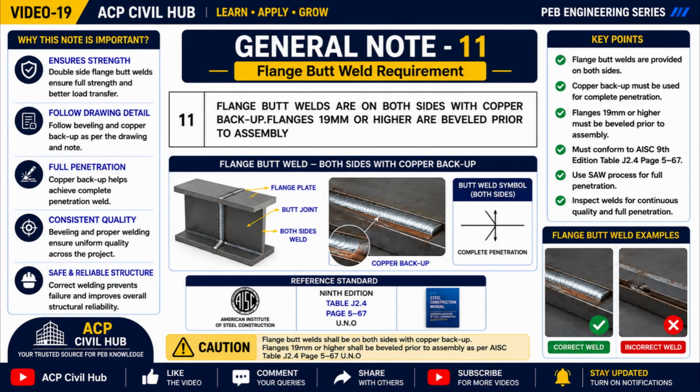The flange carries the highest bending stresses in a steel member. Therefore, the butt joint must develop the full strength of the plate without creating a weak point. To achieve this, the edges of thicker flange plates are first beveled. This groove allows the welding process to achieve complete penetration through the entire plate thickness.